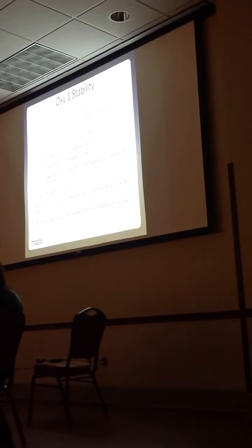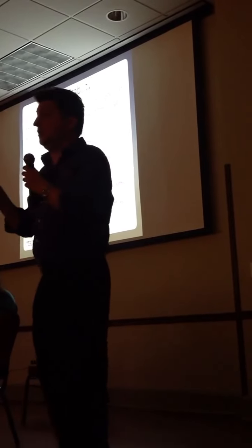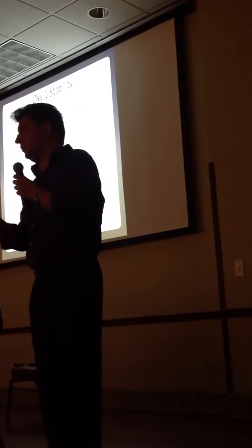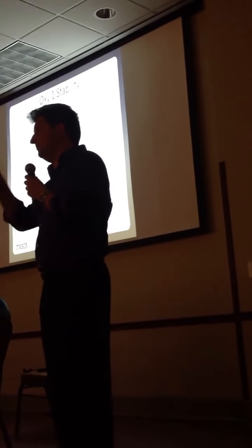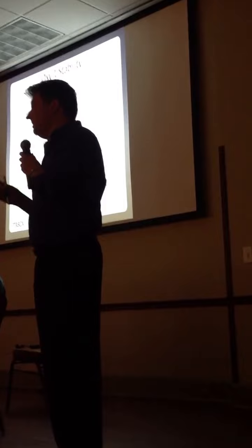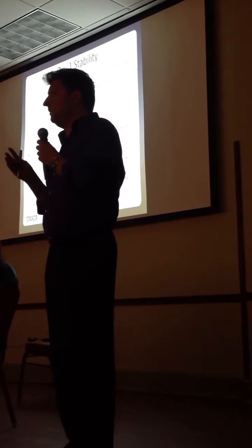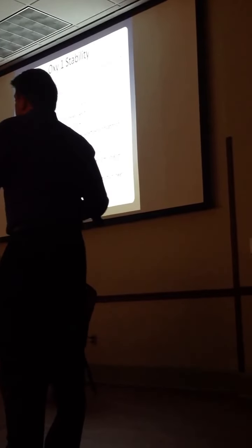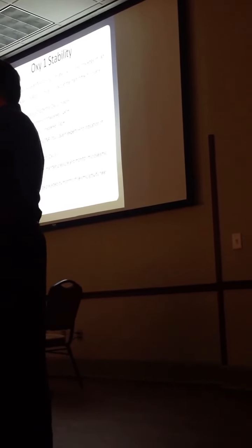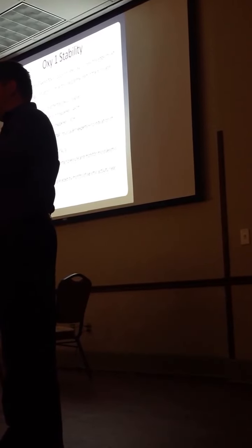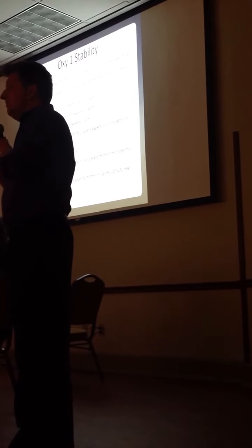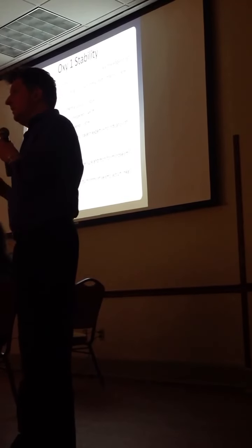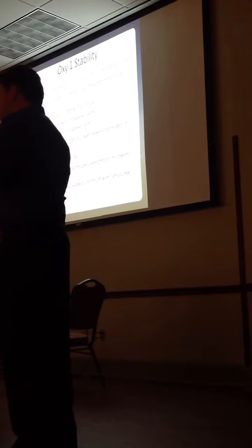The other thing that's really important is that movie that I showed you, what we believe happened there with the propagation of disturbed rock zone from 5,500 feet up to the surface. We believe that took many, many months, maybe a year or even longer. So if anything was to happen to Oxy 1, we're going to have many, many months, now that we have the instrumentation in place, many months to prepare. We're going to be able to see it happening, and we're going to be able to respond appropriately.